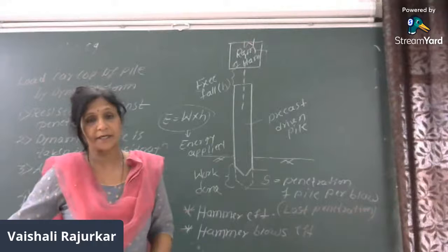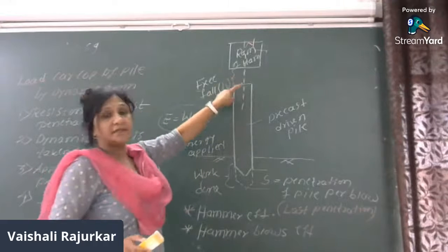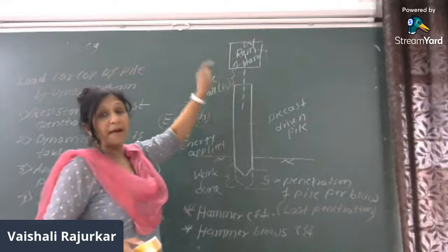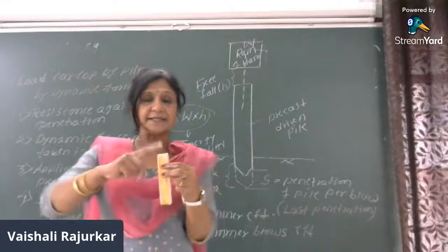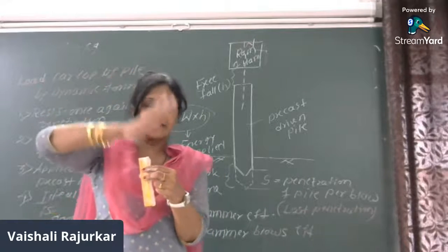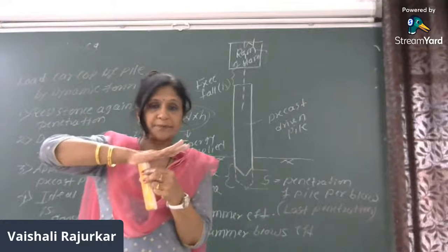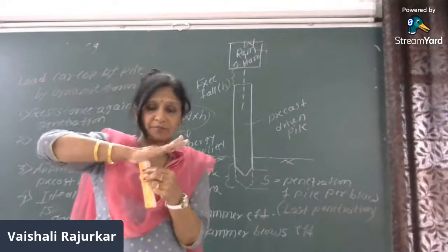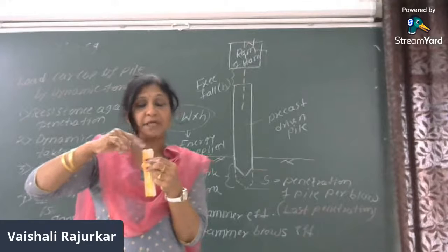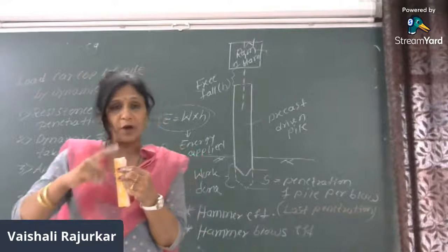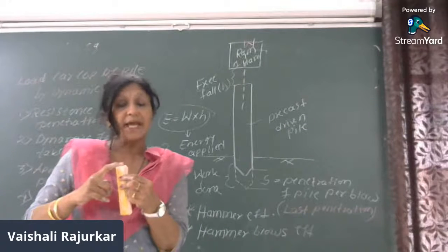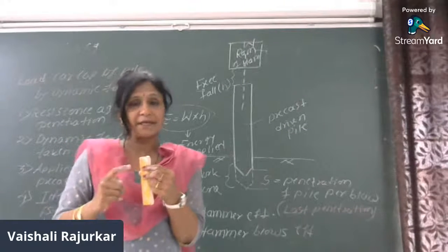Secondly, and very important, when we are driving the pile into the soil by the hammer, what may happen? Suppose I consider this is the pile, and this pile I insert with the help of a hammer. Due to the impact of the hammer, sometimes the top of the pile gets damaged and may lose material.